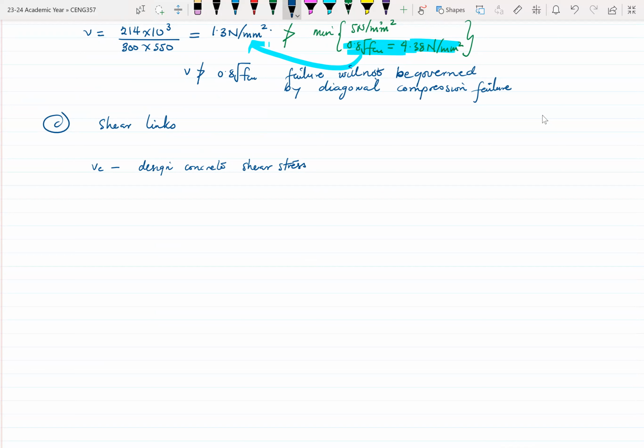All right. So to find the design shear stress for concrete VC, we need D and also 100 AS over BD. Okay.